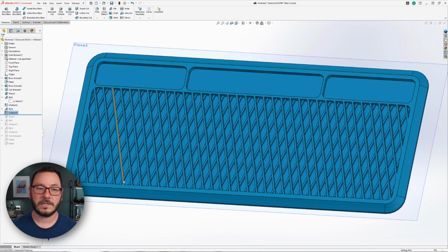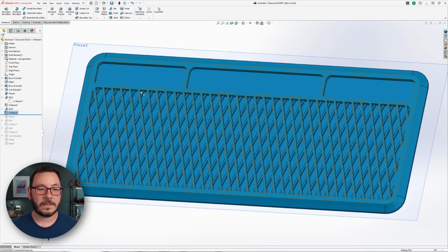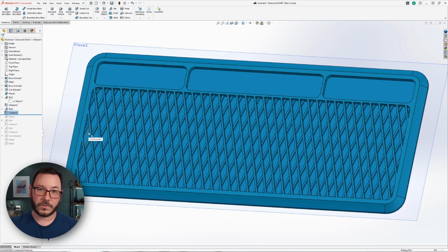Now, the other thing to consider too is that if you are drawing this geometry, chances are you're going to be molding this. These faces on the edges might all be drafted, and same with the ribs. You may have noticed in there that the rib has the ability to draft as well. So that takes in another level of complexity that you don't have to worry about. Those end conditions are just going out as far as they can in all three of those directions, and you don't have to worry about what that exact geometry is. Okay, so let's go ahead and we'll cut this back out.